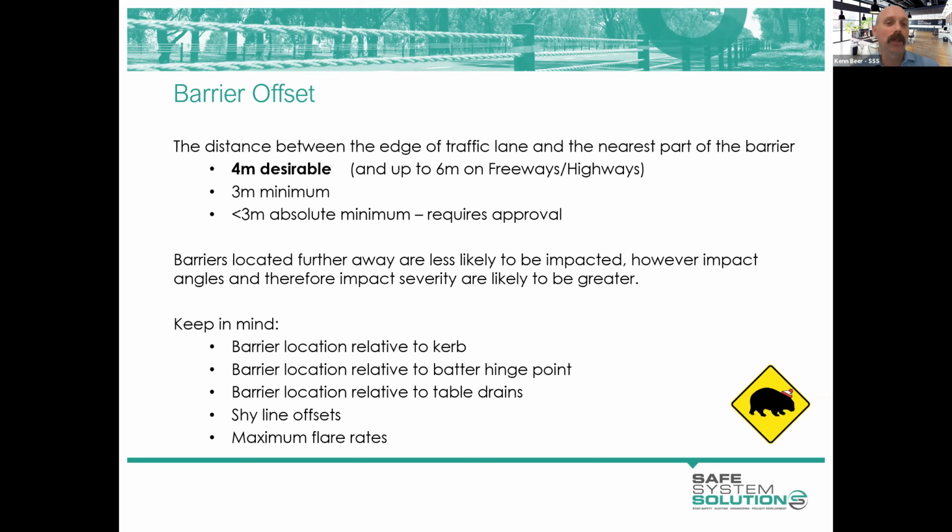Yeah, the post spacing will impact the deflection of the barrier, but not the length of need of the barrier. And protected width being the width of the hazard you're trying to protect, the amount you flare it, and the offset from edge line will all influence that length of need, as Jamie mentioned.